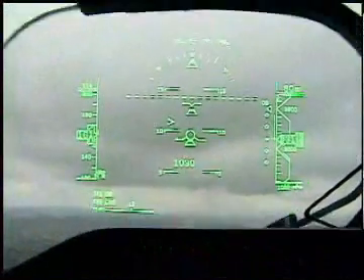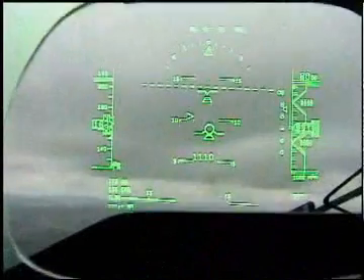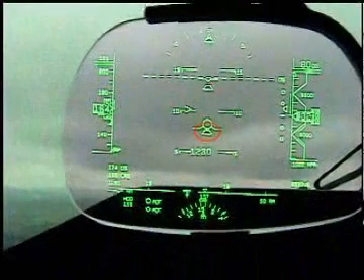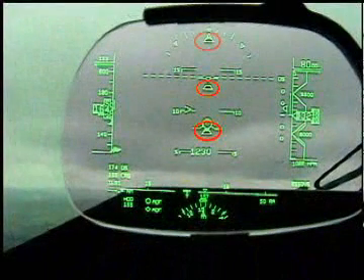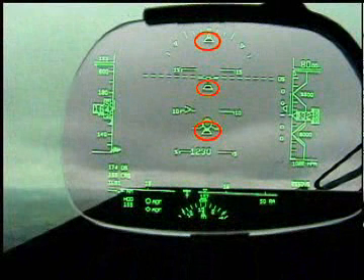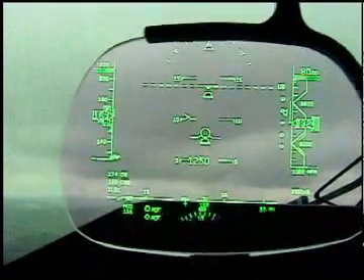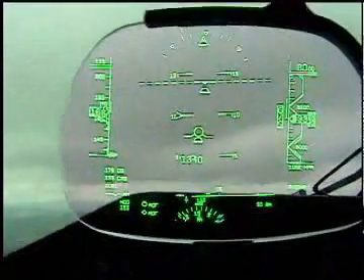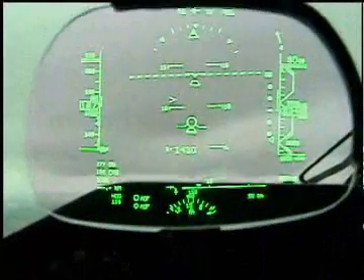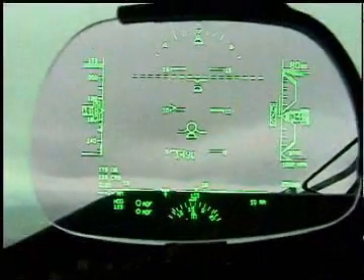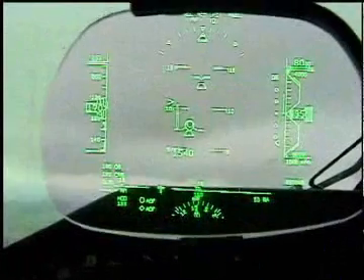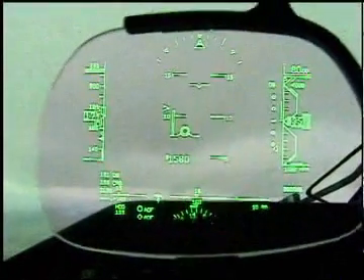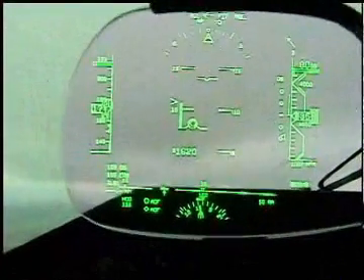Additional slip skid symbols are displayed under the aircraft reference and flight path symbols during the initial climb. These symbols are provided in addition to the roll scale slip skid symbol to enhance the lateral control of the aircraft during this phase. These additional slip skid symbols are also displayed during approach operations in the event of an engine failure. Once the aircraft is above 1,500 feet, these additional slip skid symbols are removed from the display.